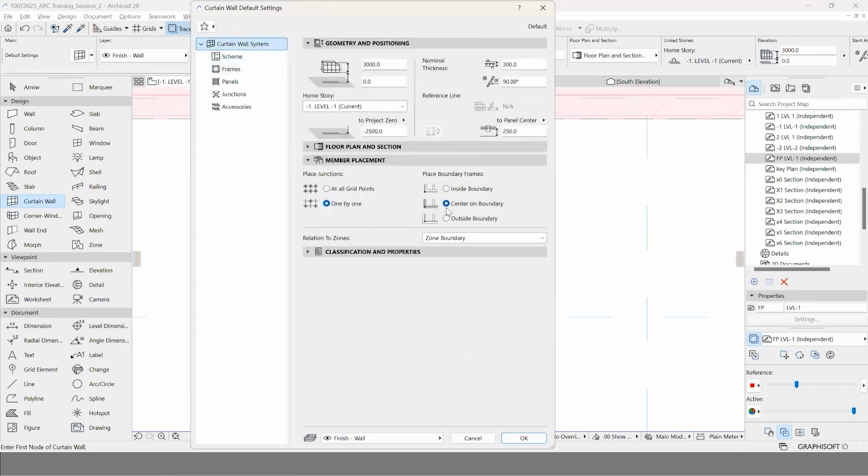Now we will go all the way back to the main settings. So these individual settings are done. Now I need to give it a height. So if I'm not wrong, it's around 2100 or 2050, 2050, I guess. Later also we can change it. So let me just give it this one only. And this is about the thickness of it. So it is going to consider more like a wall. So whatever the thickness is, you can give it here. So if it is 120, you can just give that dimension. The reason is whenever two walls come together, and if it is within that range, it will consider that it is closed. So these things will matter later for you. So just have a look at these things. But today's session, I'm not going to address all those things in detail.